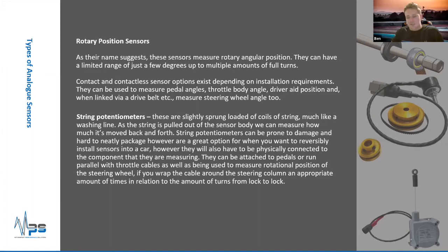So string potentiometers are a bit like a retractable washing line or airline. All it basically does is track the string's movement. It's slightly under tension, so it tries to return. So you could use it to follow a pedal throughout its movement, as long as it doesn't block your foot.